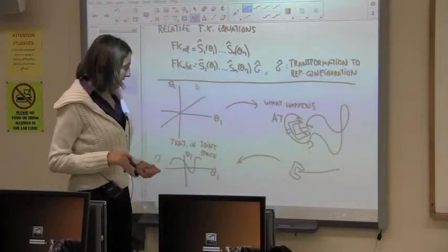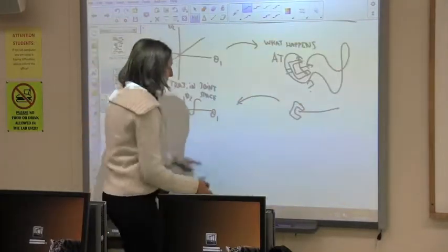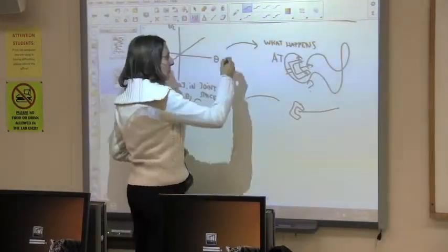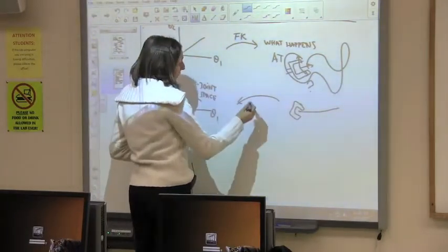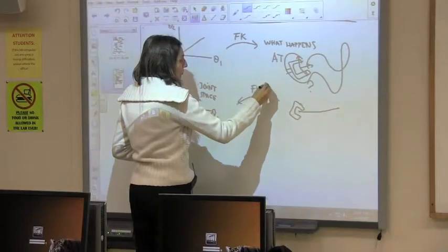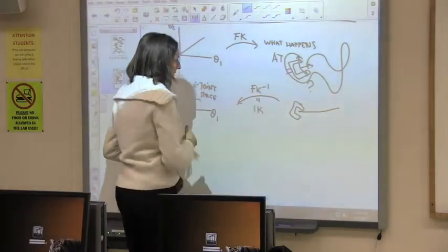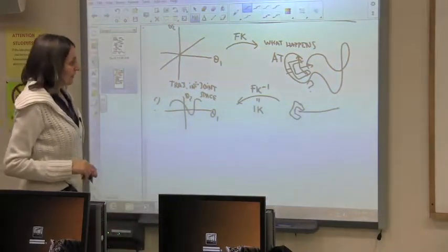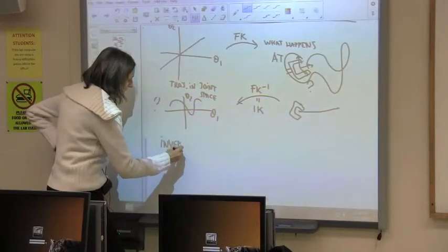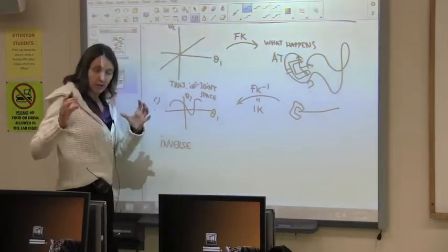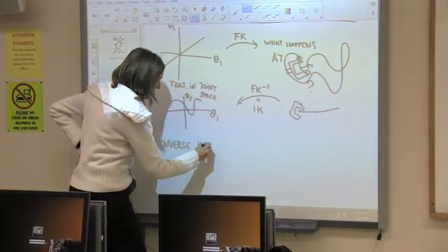You see, I knew we were missing something. We haven't talked about the inverse kinematics, but this uses the inverse mapping. Here you have the forward kinematics, and the forward kinematics to the -1 is called the inverse kinematics. We talked about what it is on the first day, but for the inverse kinematics, you use your forward kinematics mapping. You just solve for different variables. Inverse kinematics.